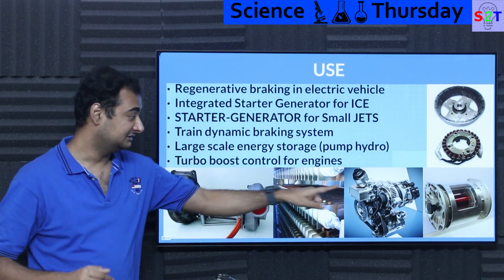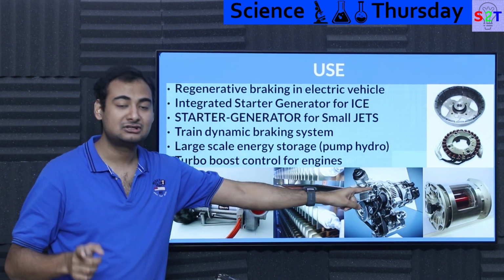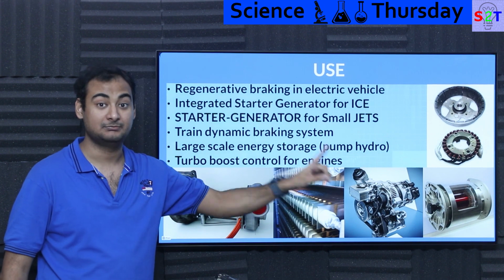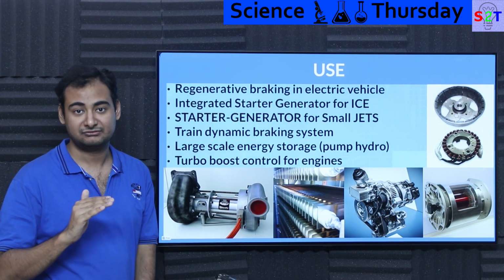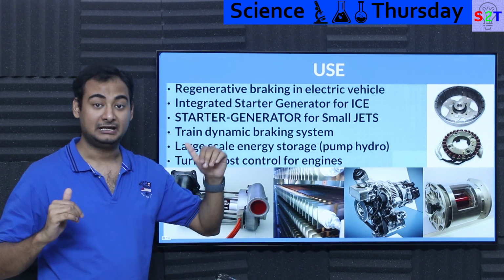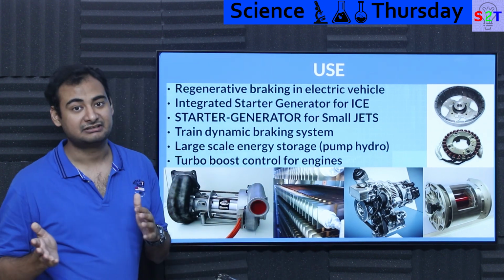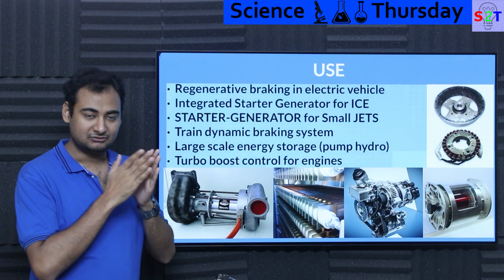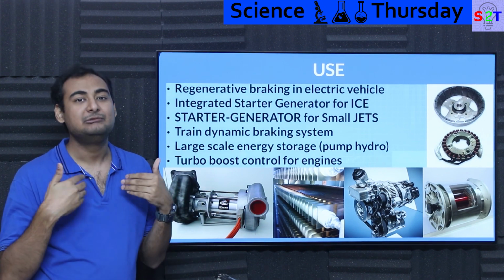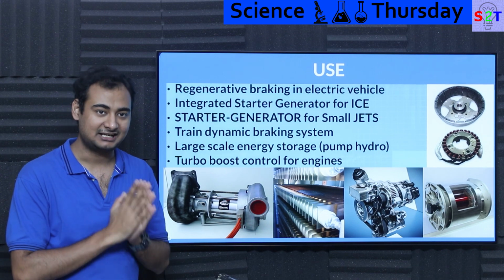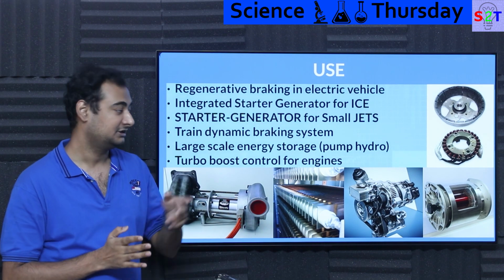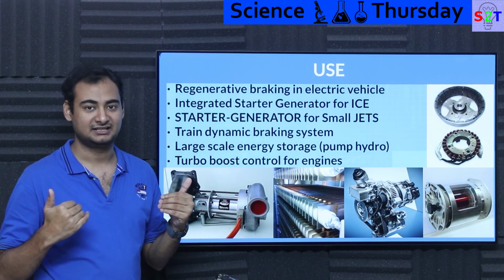But this puppy works the opposite way. It cannot stop your car. No matter what you do, it will not stop it, but it will slow it down. So if you're traveling at 100 kmph and all you want to do is bring it down to 50 kmph, this is like, I'm your friend. And the benefit of this is that brake pads on electric vehicles wear out less, because at slow speeds, we know how to make brake pads that will last inherently forever, but at high speeds, that's where they are at fault. And regenerative braking is like, high speed, I got this.